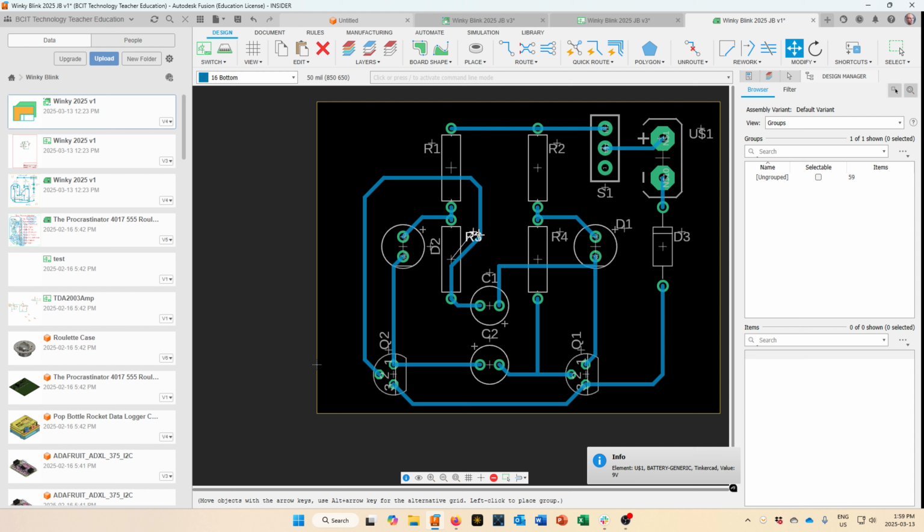Now, I'm not worried about putting this over top of the copper line right here, because remember that the text that we're moving around here, just like these outlines right here, they're all on the top layers, okay? The copper is down on the bottom layer. So technically, if you're looking at this on a printed circuit board, you'll see holes and you'll see outlines, you'll see part numbers, but you absolutely won't see the copper lines right there because they're on the other side of the board.